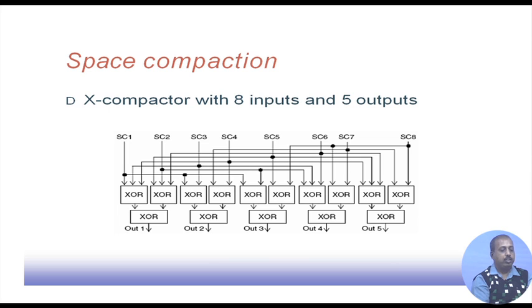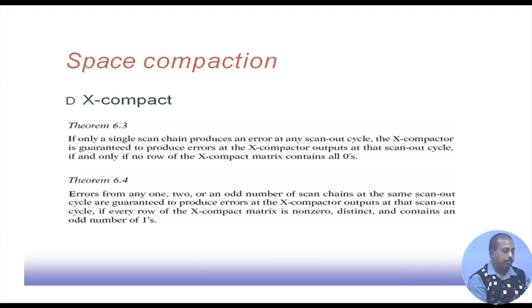So, that way it ensures that if some fault occurs and the circuit produces a different output, coming to the scan chain, so that the corresponding test pattern could detect that particular fault, then this compactor circuit is not going to lose that detection. It will pass that detection to one of the outputs, and that way it is guaranteed that aliasing will not occur; the faulty response will not match the fault free response for that particular cycle. So, this is the beauty of this XCompact scheme.